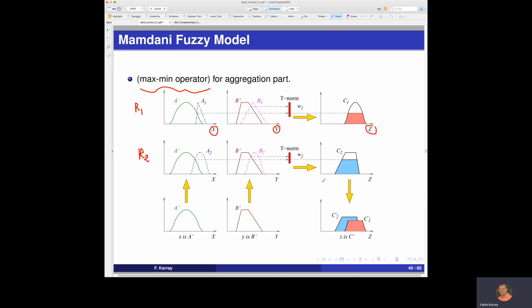We have X, we have Y, and we have Z as a consequence. And this is the context. So this is the input variable. The input variable could be a fuzzy membership function, or it could be a singleton fuzzy membership function, as I showed you earlier. In this particular case, it's a green version here, to showcase that the input is a fuzzy representation of an input, okay?